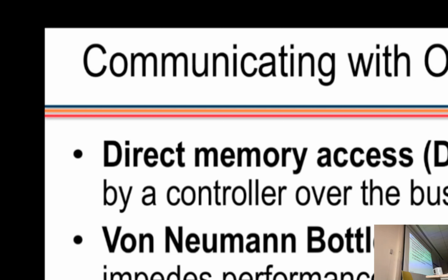when the bus speed is not sufficient, CPU is fast, but data transfer is not as good. So that slows down the whole operation. That is what we call von Neumann bottleneck. And artificial intelligence is very memory intensive, because the neural network operations require this part of the memory, this part of the memory, almost at the same time, because you have to multiply this and this right here.